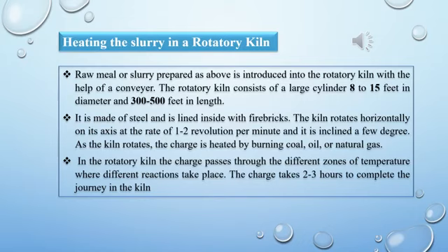In the second point, he explained that the kiln is made of steel which is lined with fire bricks, and that the kiln rotates horizontally on its axis, and the speed of its rotation is 1 to 2 revolutions in 1 minute. And he explained that the kiln is inclined at some degrees.